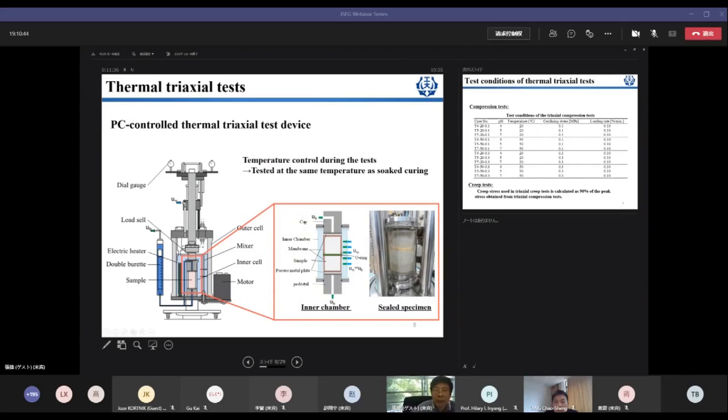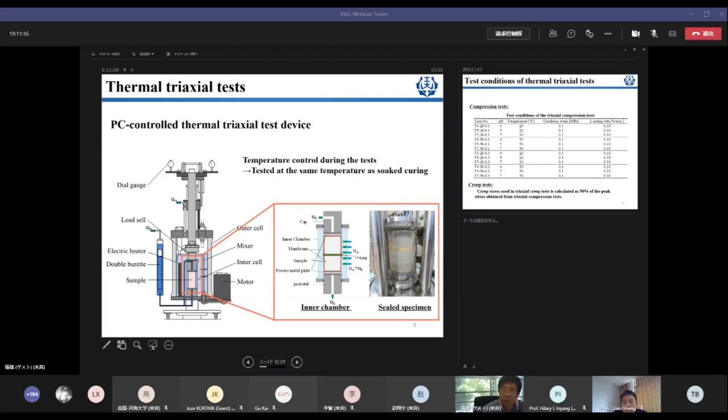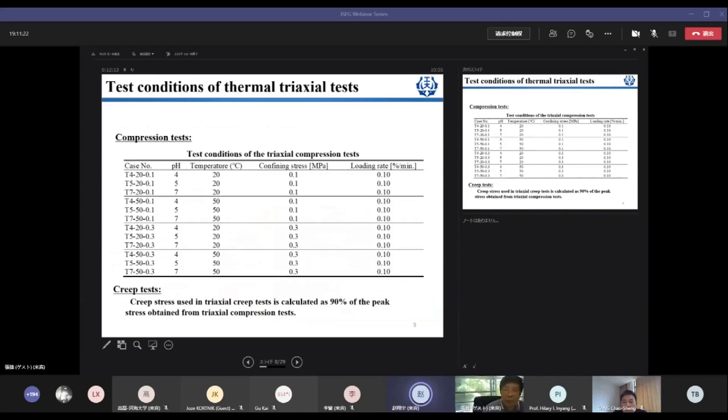So we use the techniques for unsaturated soils, using a double cell system, where you can see the cell pressure and the back pressure are totally the same. And during the deformations, the water can flow through the porous metal plates to accurately evaluate the volumetric strain, which is very important for us in modeling the mechanical behavior of the soils.